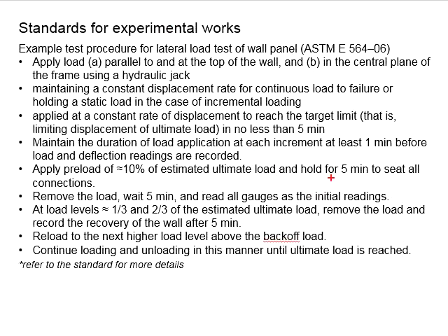You need to hold the loading for 5 minutes before you remove the load, and then wait for another 5 minutes and set all the gauges as the initial readings. That means you are about to officially start the testing. This process is quite important as a preparation for your testing.